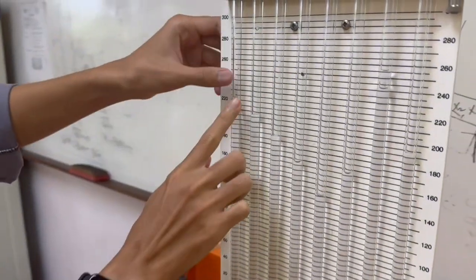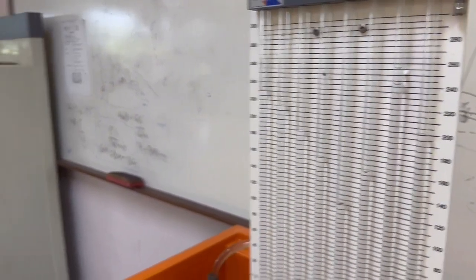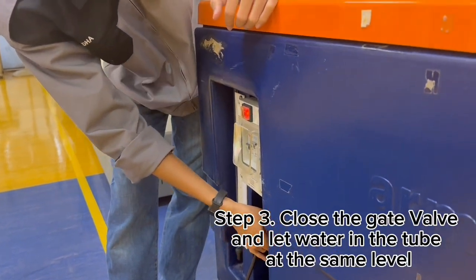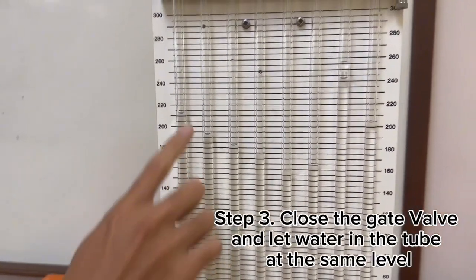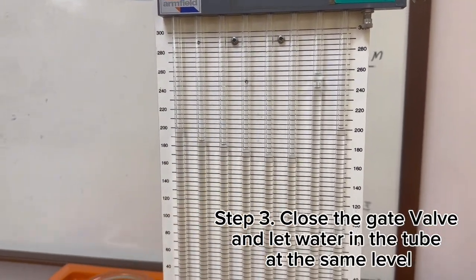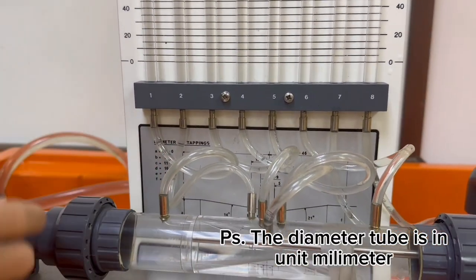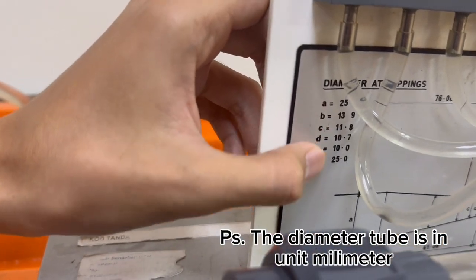Make sure that the water flows and all the bubbles inside the tubes go outside. Then you can close the gate valve. After that, make sure all the water in tubes number 1 to number 6 is at the same level. The diameter of each tube is already given, in millimeters.